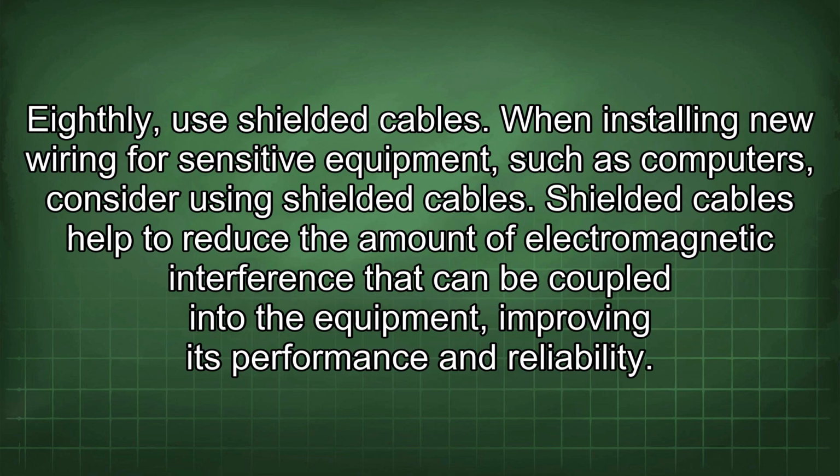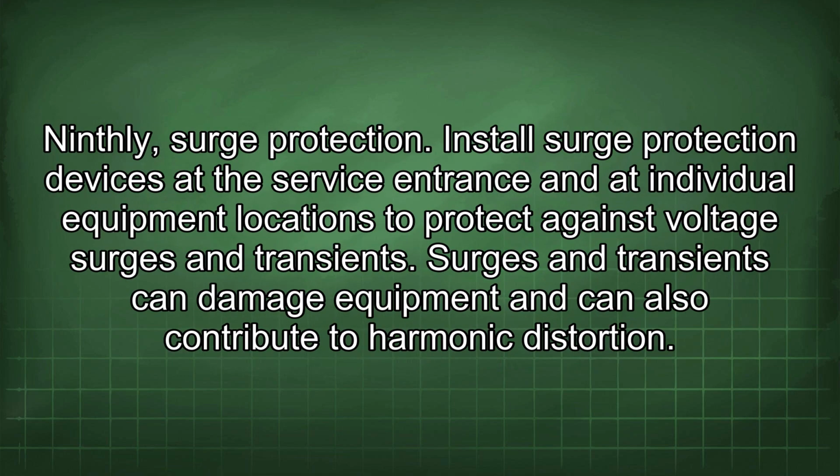Eighthly, use shielded cables. When installing new wiring for sensitive equipment, such as computers, consider using shielded cables. Shielded cables help to reduce the amount of electromagnetic interference that can be coupled into the equipment, improving its performance and reliability. Ninthly, surge protection.